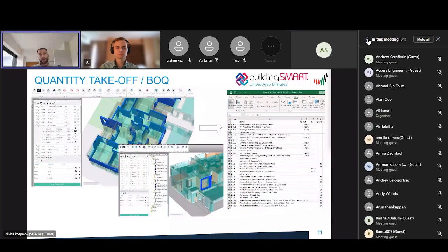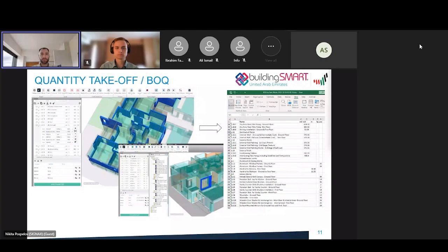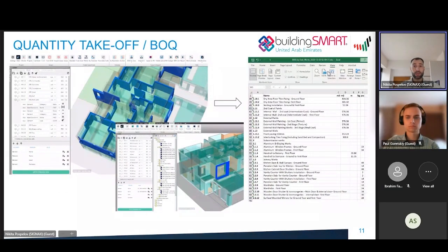We have empowered classic Navisworks with extremely convenient tools for calculating quantity takeoffs and bills of materials. In one program interface, we create a WBS structure with units and unit prices, and add rules to filter out specific elements or groups of elements. After that, we can extract all quantities in the desired format connected to accurate BIM scope.